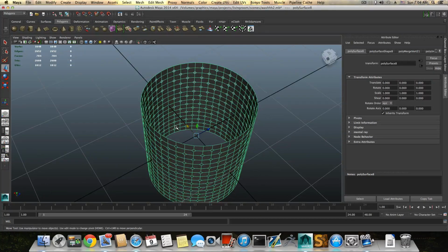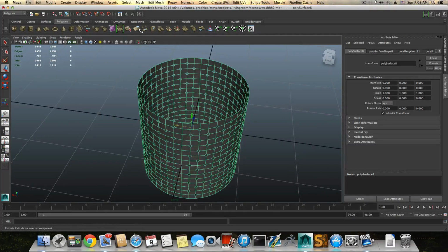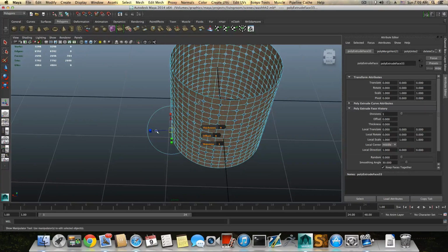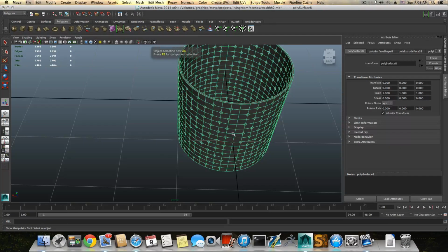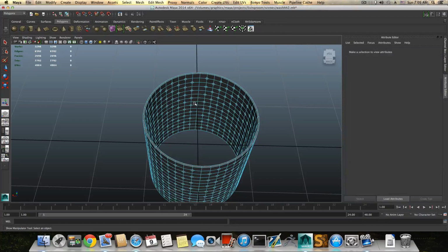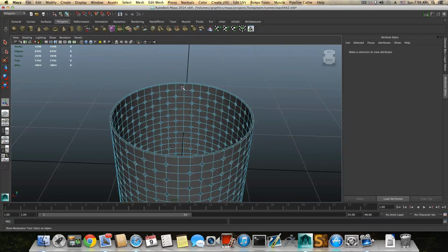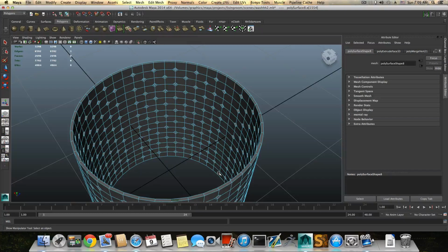And now I want you to extrude this and pull this blue arrow a little bit out like so. Press F8 once or twice, and then right click, choose edge. First thing is to grab this edge, you see this here, and shift double click this one, so it will select everything in between.